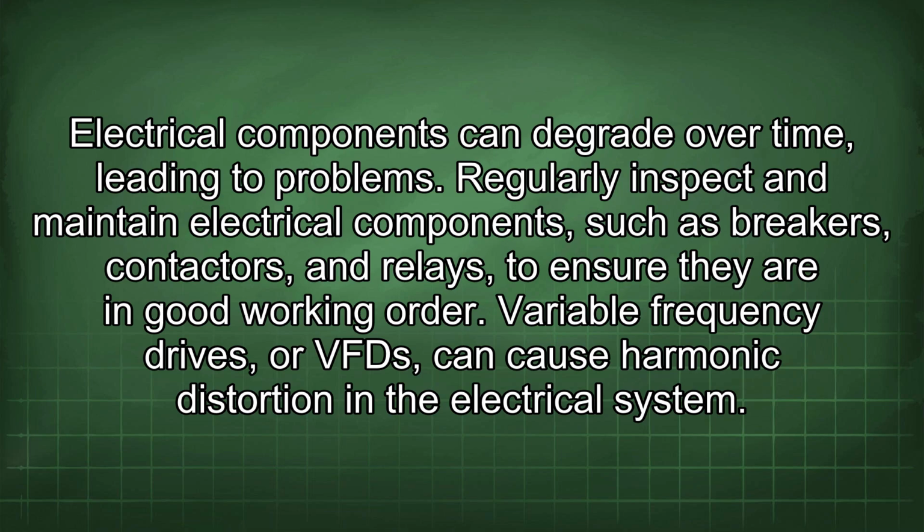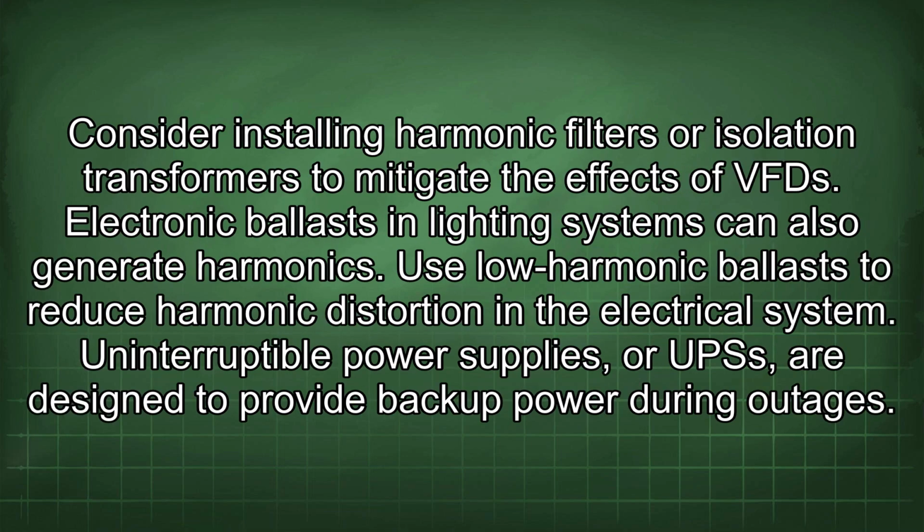Variable frequency drives, or VFDs, can cause harmonic distortion in the electrical system. Consider installing harmonic filters or isolation transformers to mitigate the effects of VFDs. Electronic ballasts in lighting systems can also generate harmonics. Use low harmonic ballasts to reduce harmonic distortion in the electrical system.